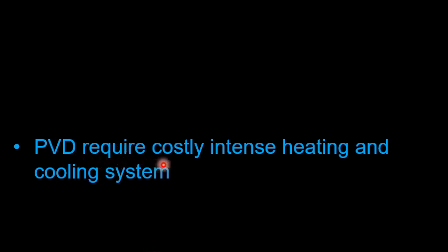Another drawback of PVD is the cooling system. You also need a cooling system, because in PVD you use hundreds of kilovolts of energy from the electron beam, from the pulsed laser, or by sputtering. So when you bombard the source material with an electron beam, pulsed laser, or by high energetic ions of the sputtered source, basically the surface of the source material heats up to thousands of degrees Kelvin.